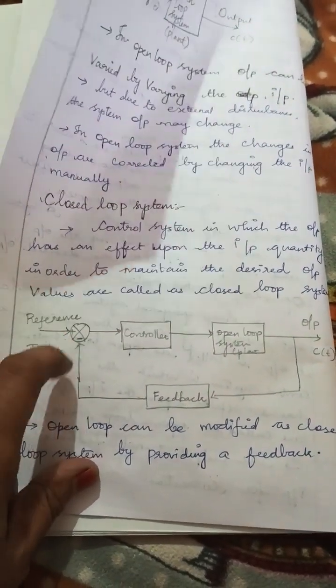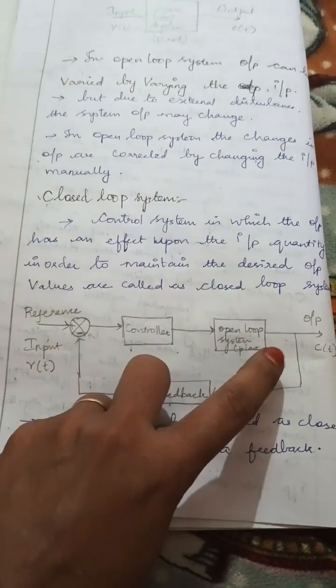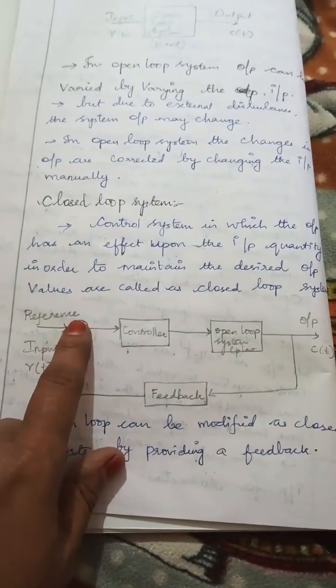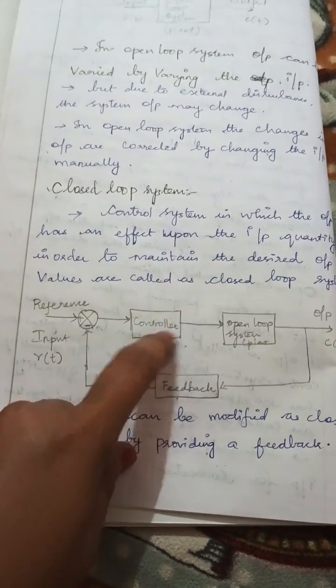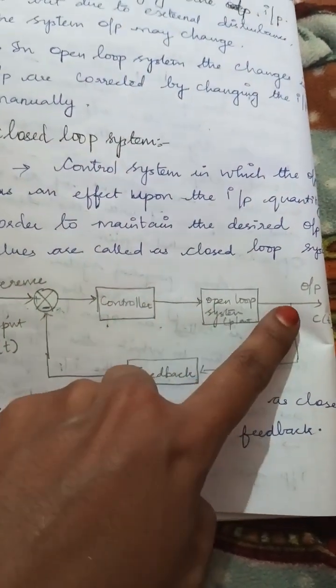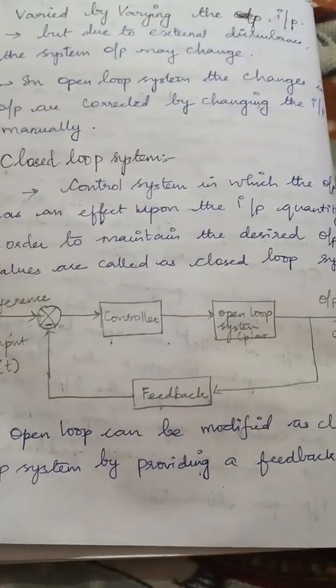The difference of the signals is given again to this controller, such that if any output performance was not good, relevant to this feedback the system performance gets controlled, and correspondingly we get an output. So if the output is fed back to the input, we call such a system a closed loop system.